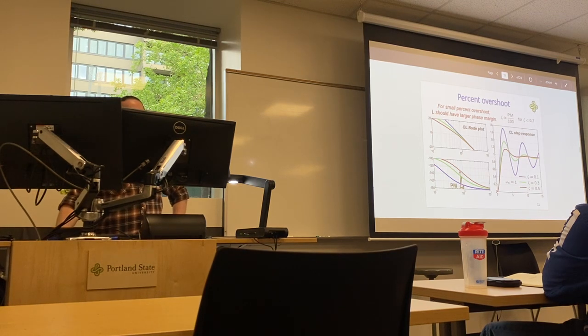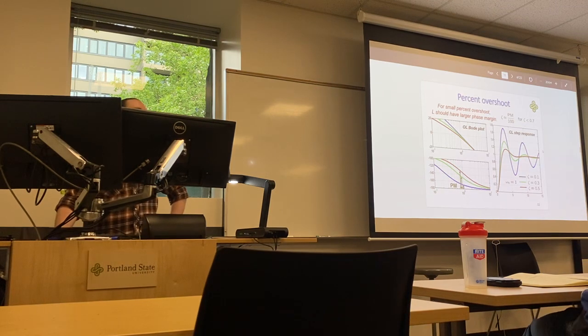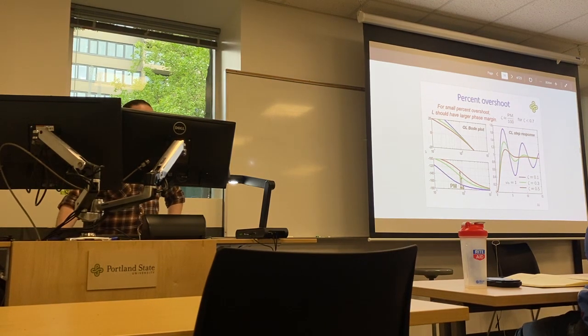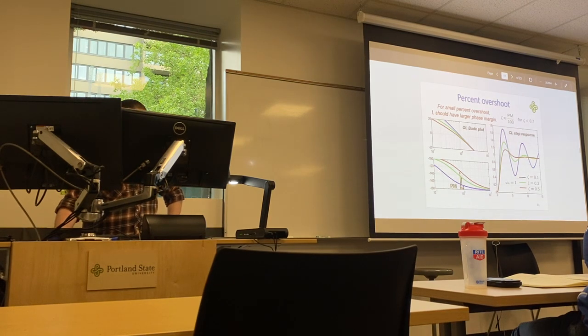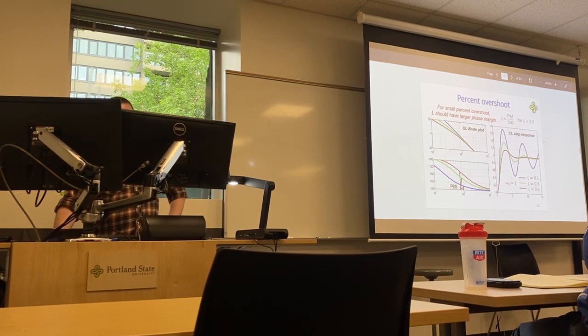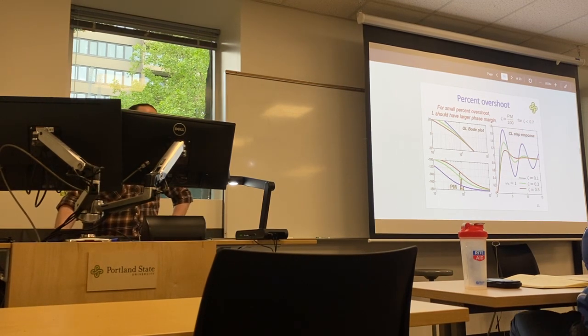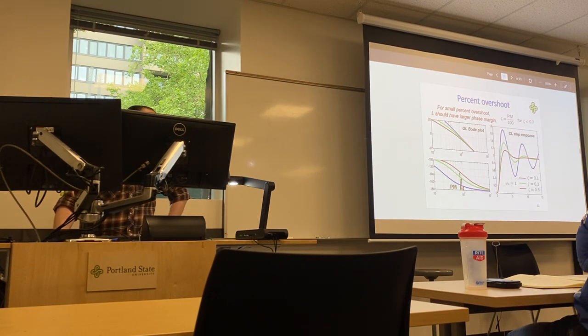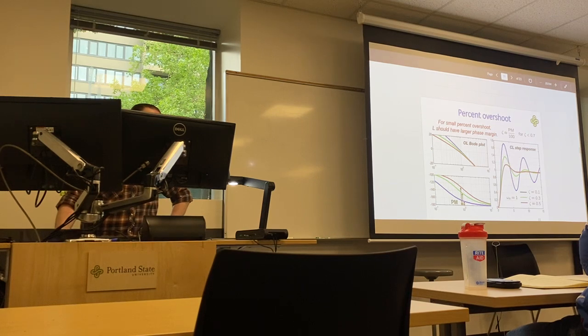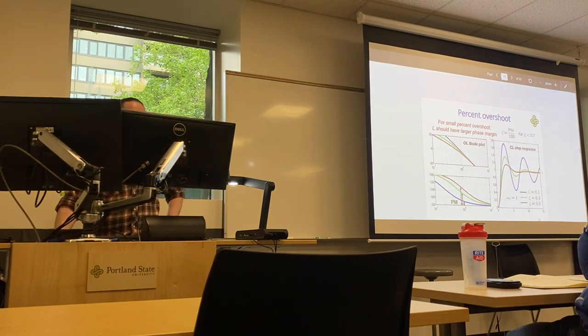So we see here with a higher damping ratio, we get more oscillations that take more time to settle out, but also our phase margin decreases much more rapidly, leaving us less phase margin and causing more percent overshoot. You also see we end up with higher gain, which if we're designing for that steady state accuracy would be good, but it takes a lot longer to settle out.